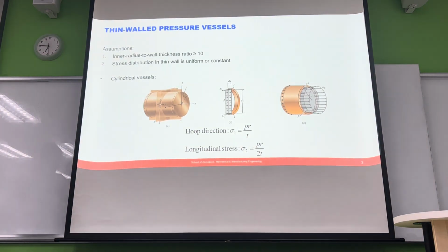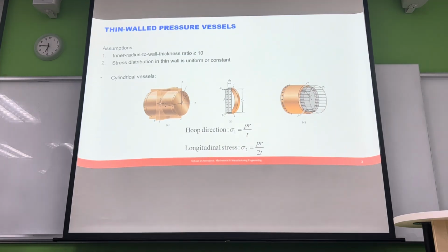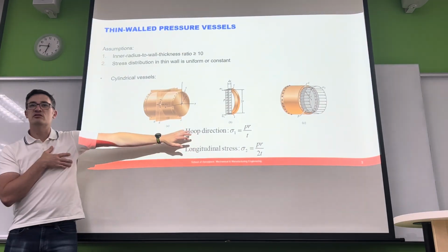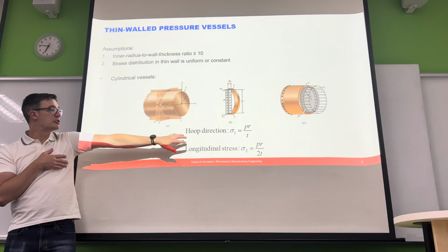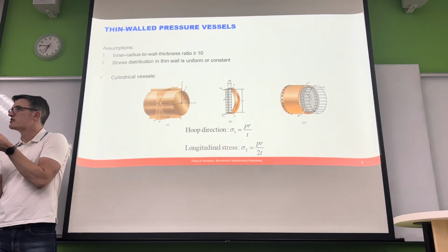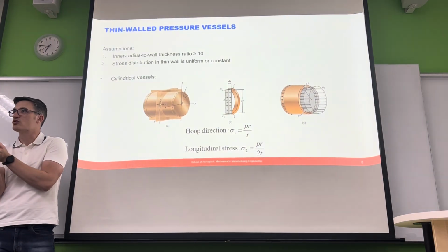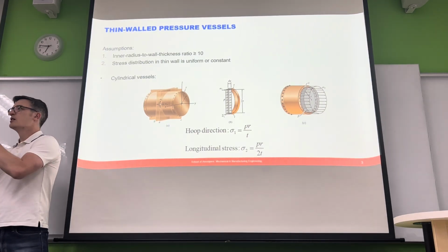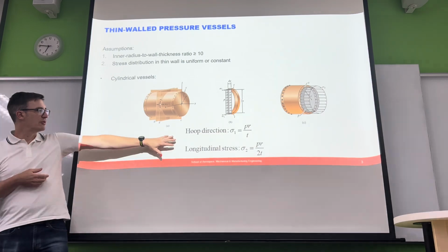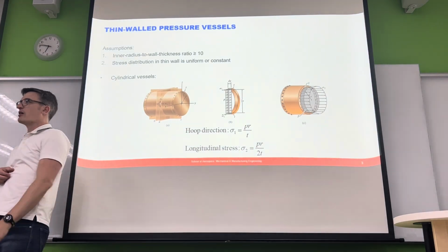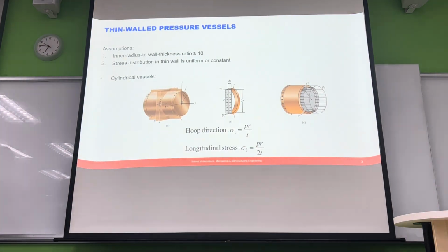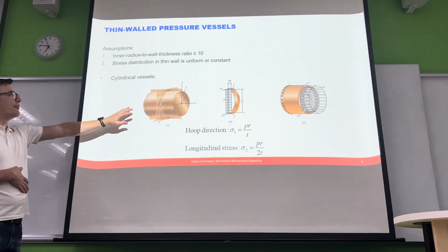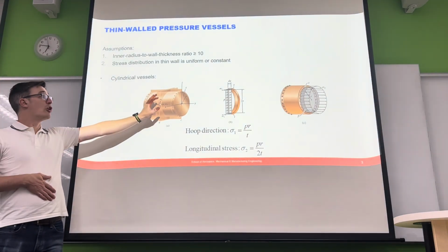It's got multiple different pressure vessels inside of it, and we used these exact formulas to give us a rough estimation of how thick we should make the structure. Initially, when the people first did the design, they thought it should be 4.5 millimeters thick, and when we put these numbers in, we were able to do a quick analysis and say, we don't need it to be 4.5 millimeters thick, it can be like 1.5 millimeters thick, and we save a lot of weight and a lot of cost as well.